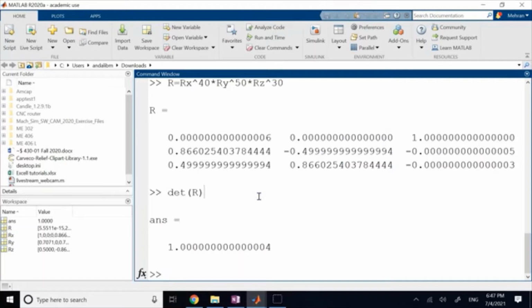So let's say this control loop has a sample time of, let's say, 10 milliseconds, and your total time to go from position 1 to position 2 is like 2 seconds, right? So 2 seconds with a sample time of 0.01, it means what? 200 samples, which means 200 different rotation matrices that were calculated each time.